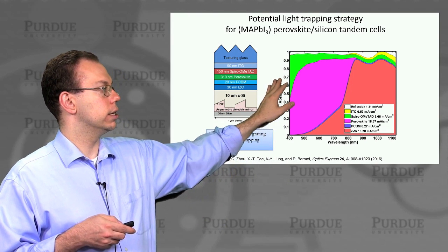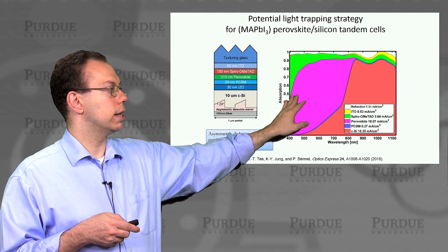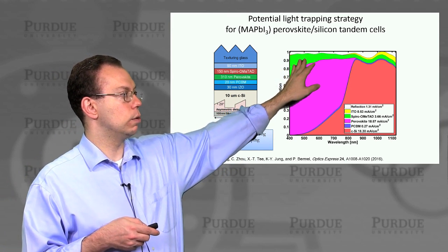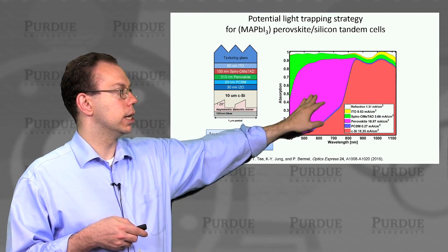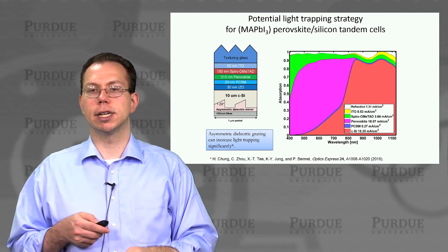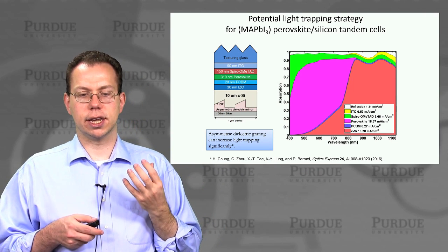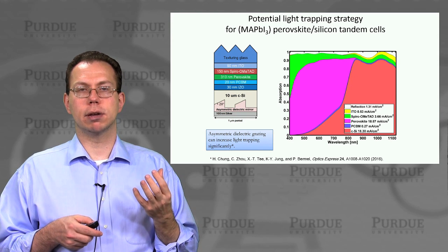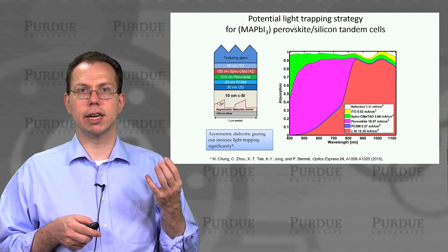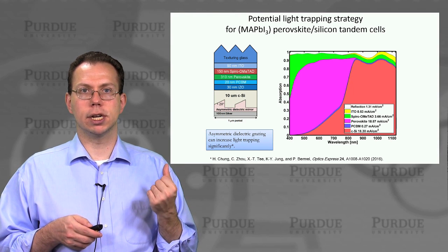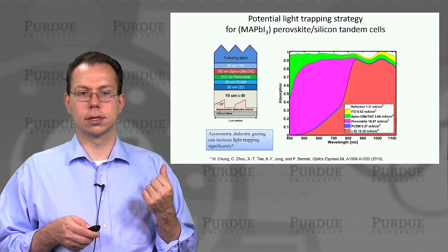And then we can directly capture what kind of absorption is happening, and then what parasitic losses, including the spiro-MeOTAD, some reflection, and then a couple other loss mechanisms, which are relatively small, like the indium tin oxide. And then that gives us a very clear indication of the potential efficiency, perhaps could be up to 25 to 28% for these tandem cells, which is pretty significant.